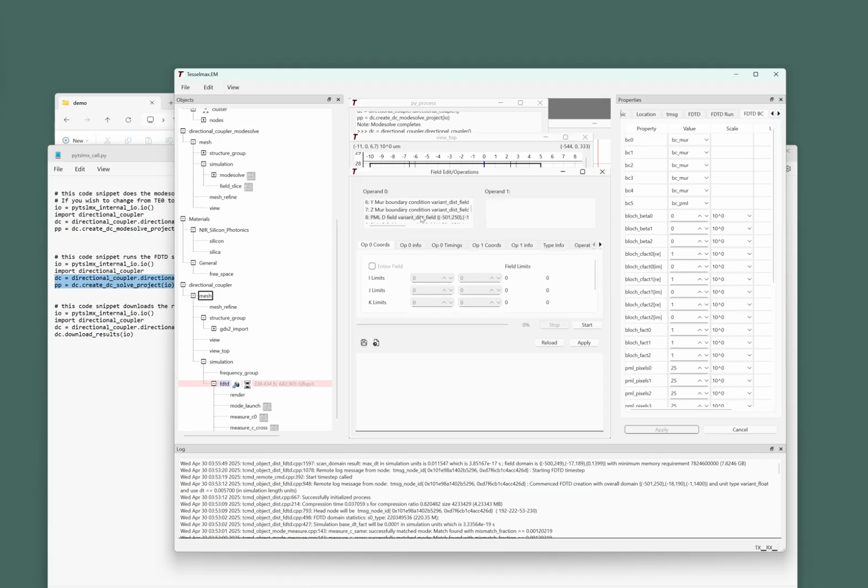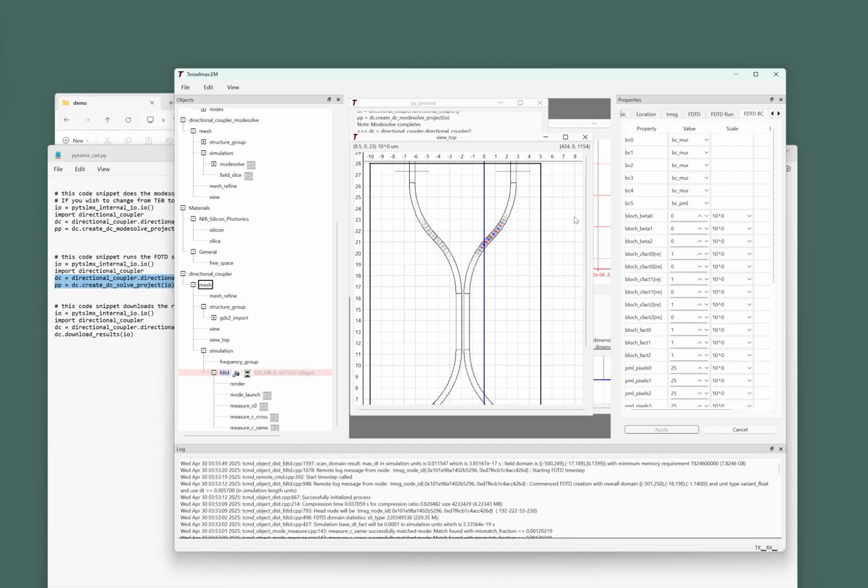Yeah, see the actual raw fields are there and you can go and simply download from a given grid point or range of grid points what the field is. You can even upload something if you'd like to any of the fields involved, whether it be structural or E or H. And if you upload some random field value to something in the middle of an FDTD simulation, I am sure it will cause a problem and be non-physical. Just in case that was a question. Yeah, so I didn't edit anything or change anything.